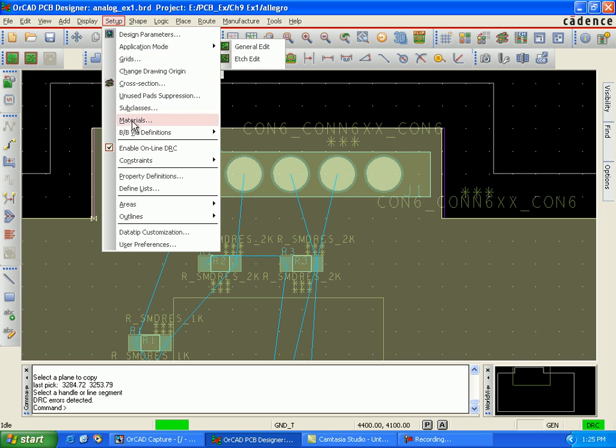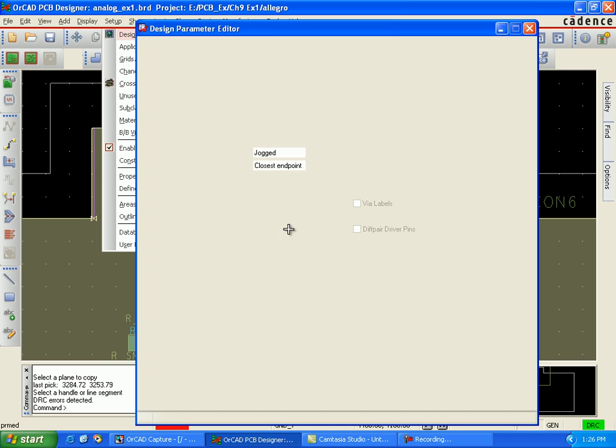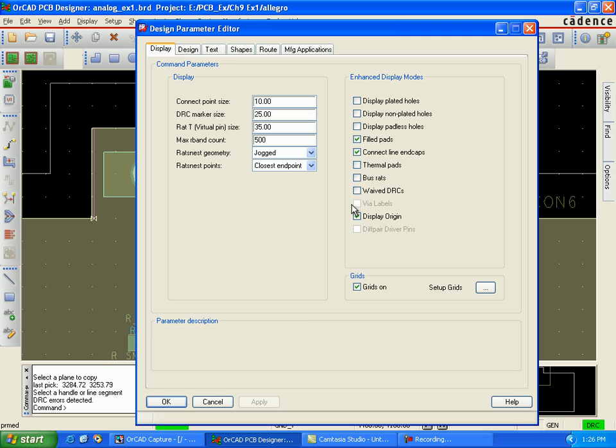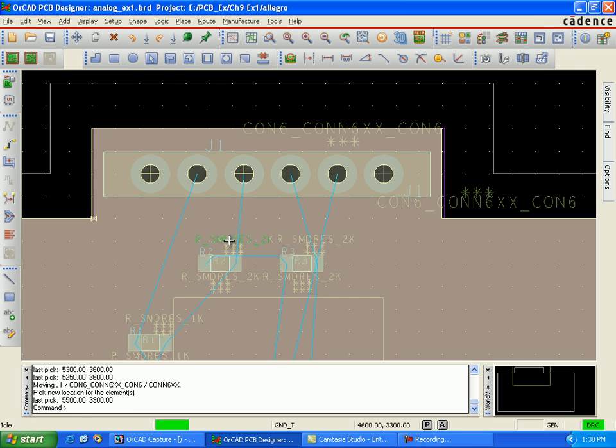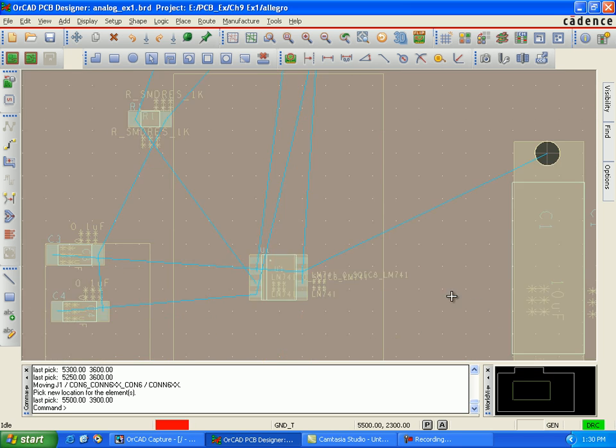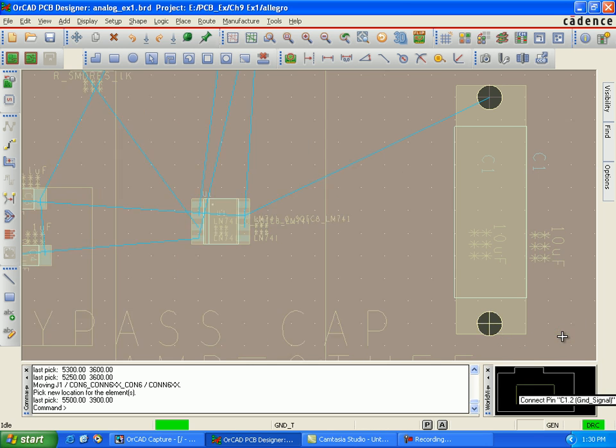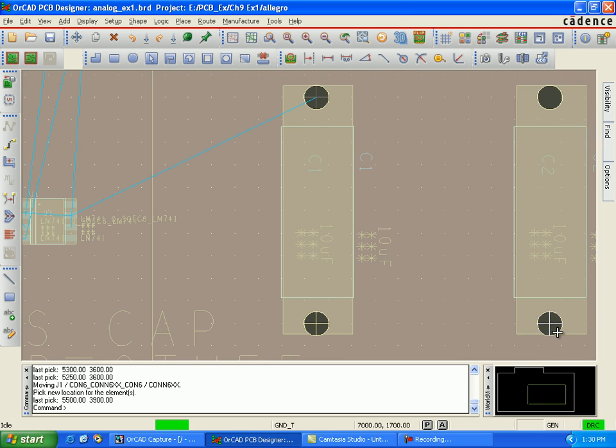We're going to verify the thermal pads because we are using assembly components, and there are times when we do not want too much heat to solder because it may cause trouble. So we give a thermal pad, with certain patterns to the copper surrounding the pad and the solder mask, which helps to dissipate the heat in such a way that we only get the heat where we need it, not too much, which can cause a problem to the board and the component connections.